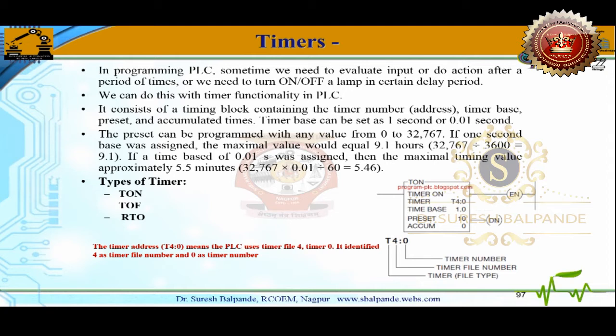And third is the retentive timer, that is RTO. The basic difference between these three is that the TON timer will turn on after the specified delay. The TOF timer will immediately turn on and it will turn off after that specified delay.